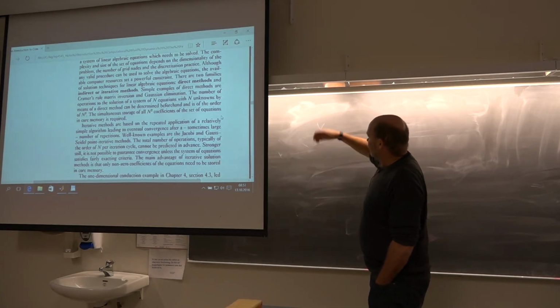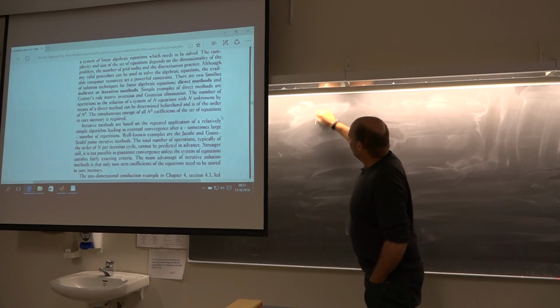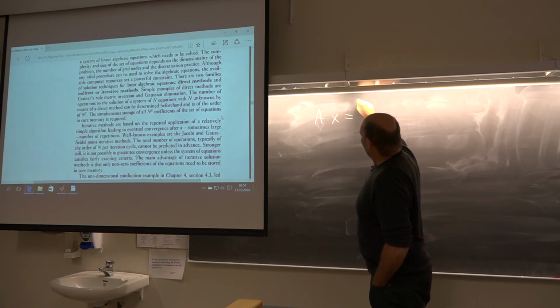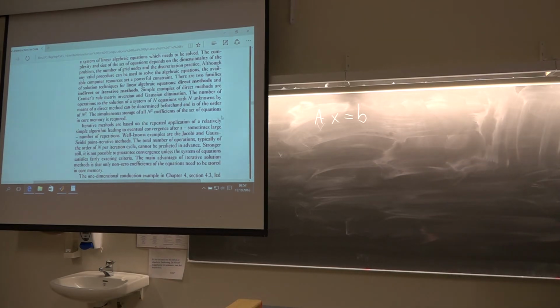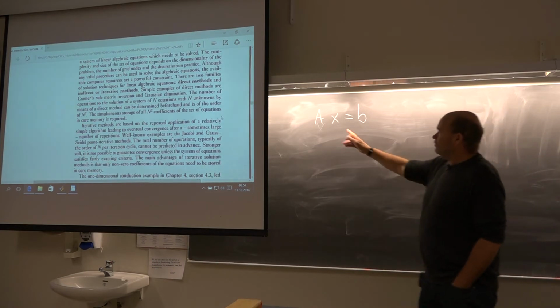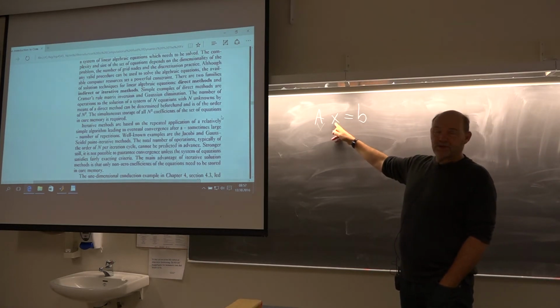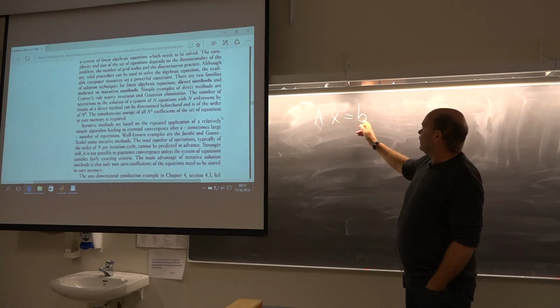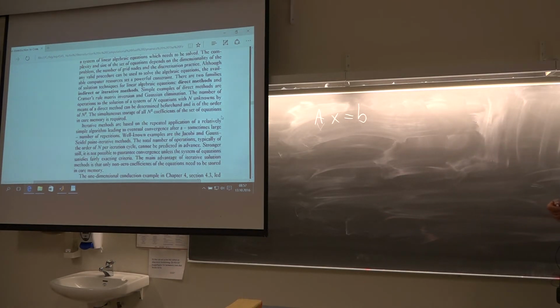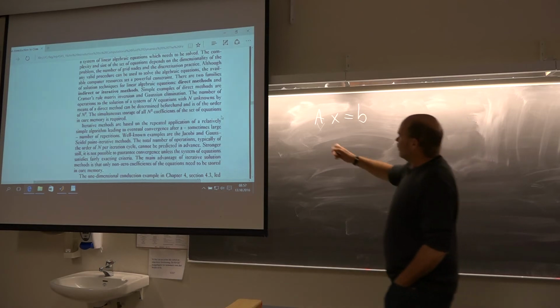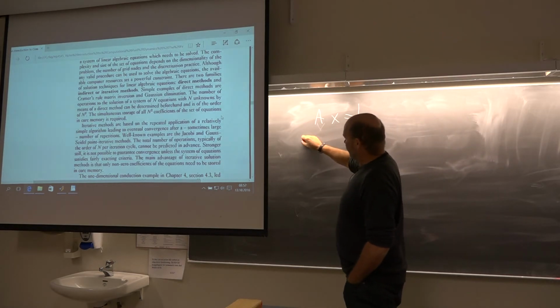So for the equation system, you can always write it like this: AX equals B. A being a complete coefficient matrix. X, all your unknowns, velocities, pressure, whatever. B, the constant or not constant right-hand side of your equation system. The coefficient matrix A is going to be very, very big.